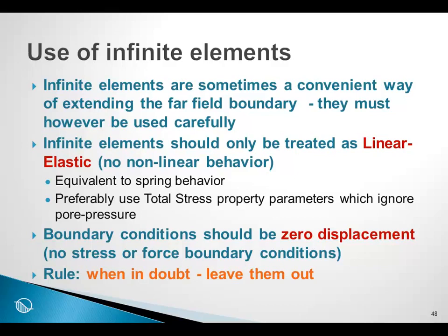Basically, you can think of infinite elements as springs. The far field boundaries of the problem, in essence, have spring-like behavior when we use linear elastic properties for the infinite elements. Furthermore, often it's preferable to use total stress property parameters because they ignore any change in pore pressure in the far field.